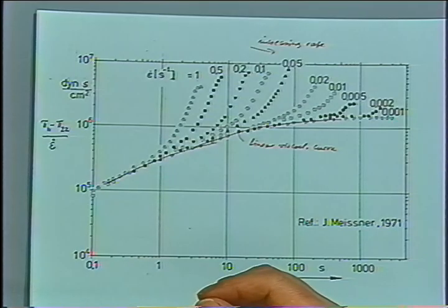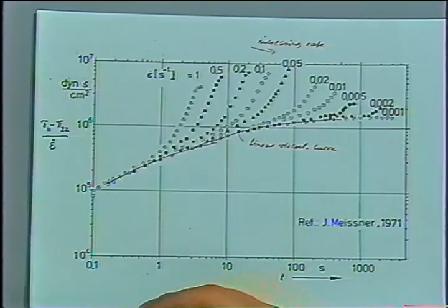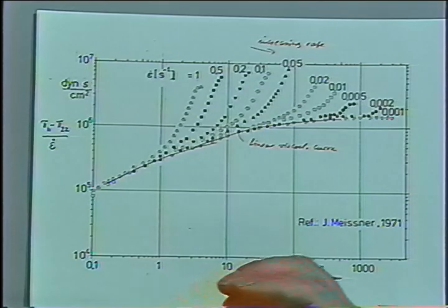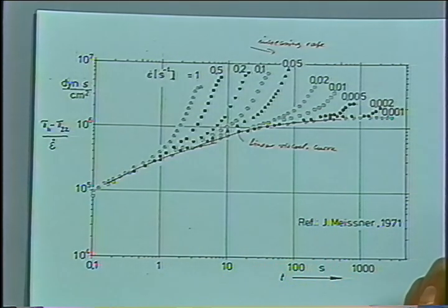And then your transducer value is biased by noise. Also, the measurement might be biased by surface effects. The ratio of surface to volume increases drastically when your fiber gets very thin. And then you might not measure bulk properties by themselves, but you might measure a combination of bulk property and surface property.